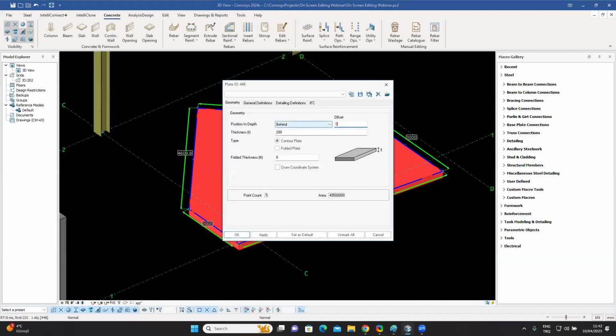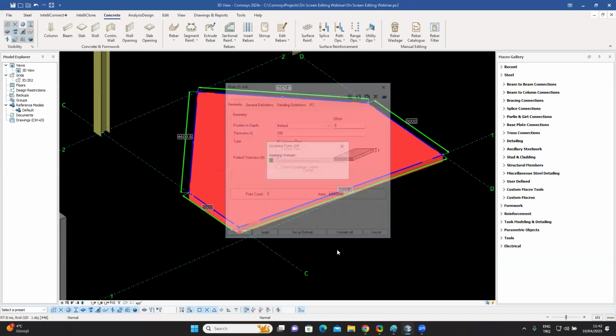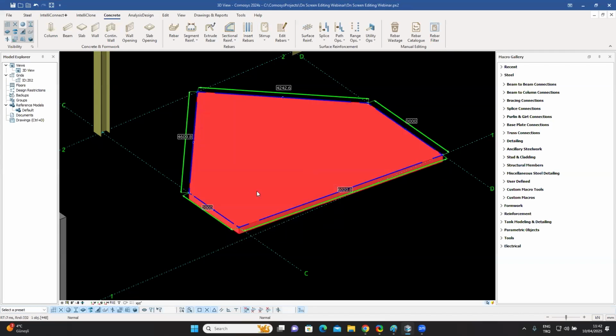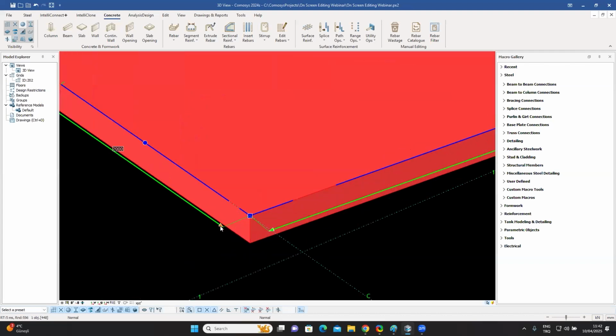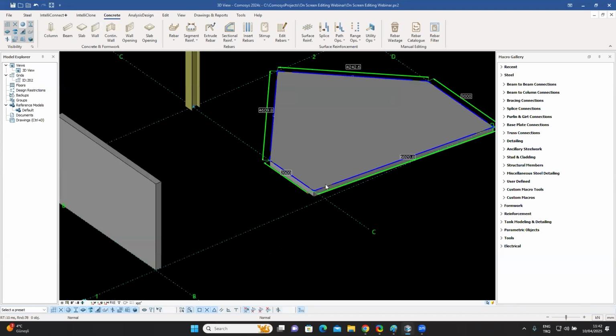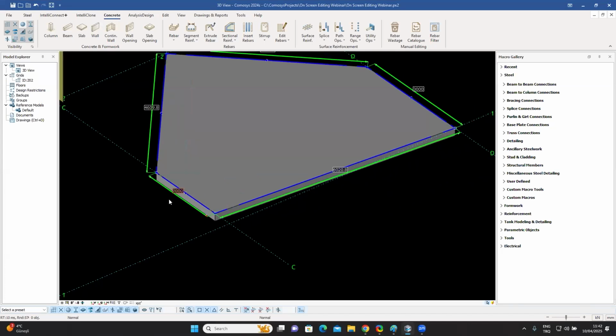Let me just remove the offsets over here. So if I select it, I can press Control W, and you can see that the plate is being offset like that. If I select the plate, once again, you have the same handles, the arrow, the endpoints. If I select the arrow, I get the same. I can move it a number, or I can make it extend to a surface, just like we did last time. I can introduce midpoints as well.